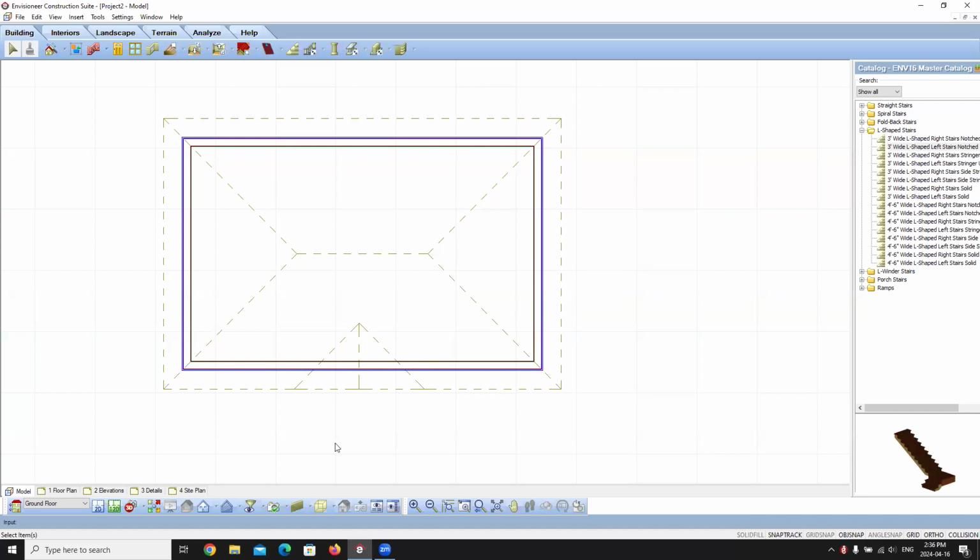Using the dormer tool will allow you to insert a dormer on an existing roof surface. And to create a gabled portion in the middle of a fascia, you can break the roof edges at 2 points to create a new roof segment. Then select the new segment and change it to be a gable style. For any roofs that need further editing than what you can control with the parametric roof, you can convert your roof edges into surfaces to manipulate them.